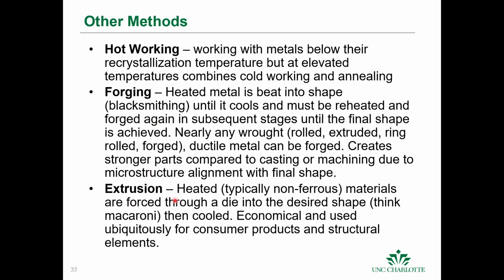And then you have extrusion. Basically, you heat up a piece of metal and smash it through a die, like a piece of pasta or macaroni, and then you cool it. This is actually quite economical. It's also used ubiquitously for tons of consumer goods, frames, windows, all sorts of stuff, where we can have these tiny little extrusions. We can do L brackets, channels, etc. for structural components, and it's a very good way of making materials.